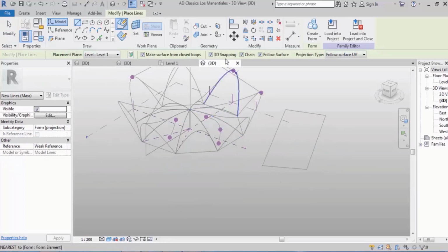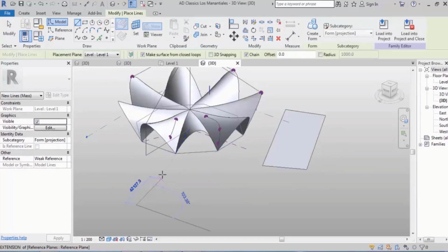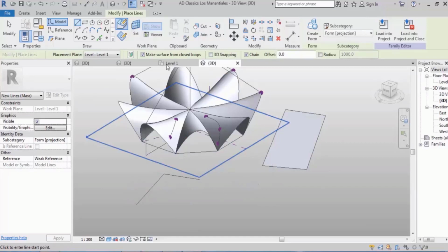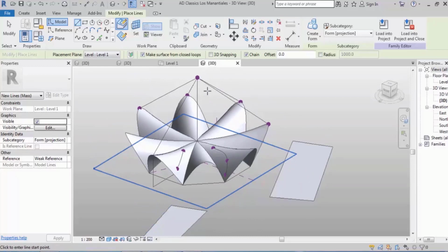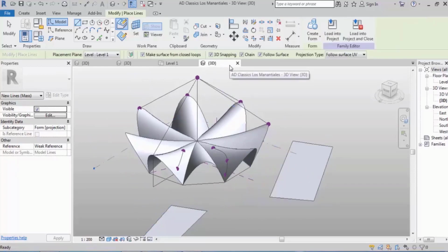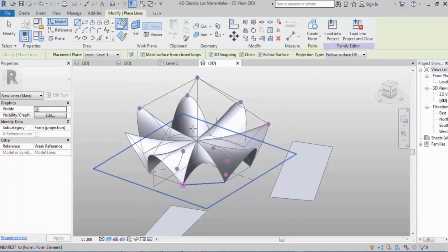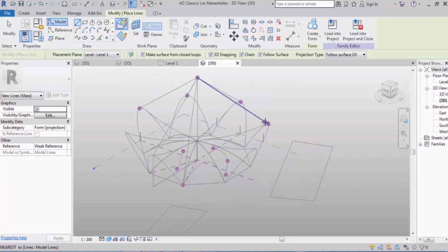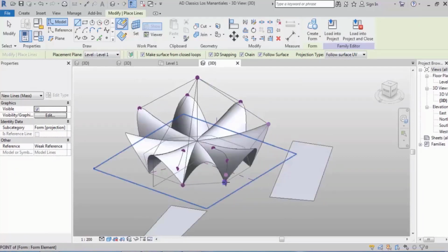Now, when I pick it, let me activate my 3D snapping. I design it, and then I connect it. You see, yet it becomes a sheet. So finally, if your design ends up as a closed shape, it will be turned into a sheet. And of course, if you've already clicked on 3D snapping, you are capable of creating a closed sheet in space.